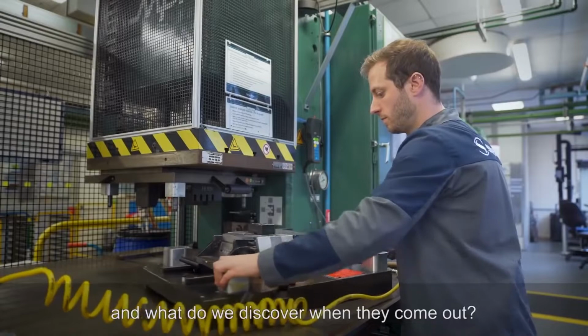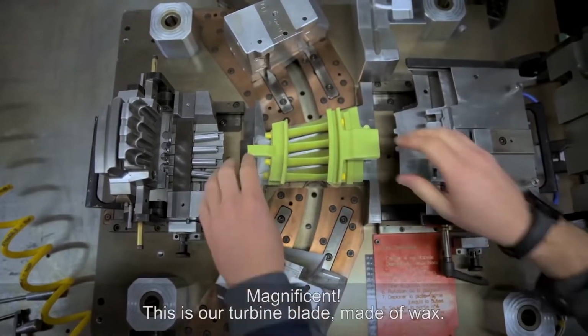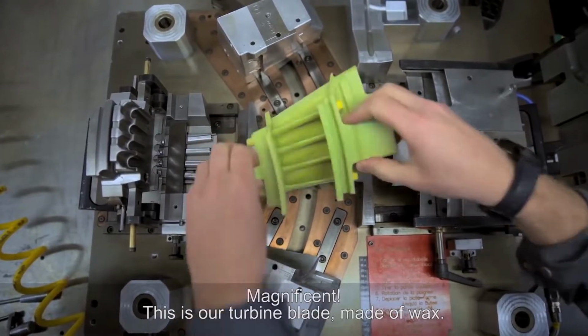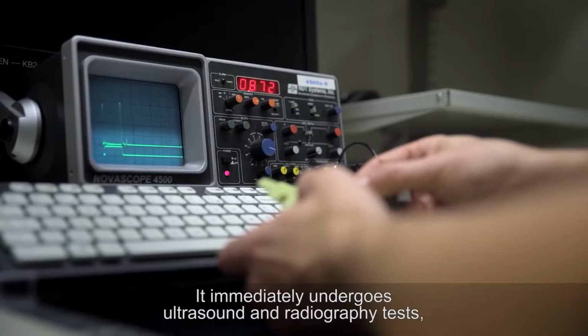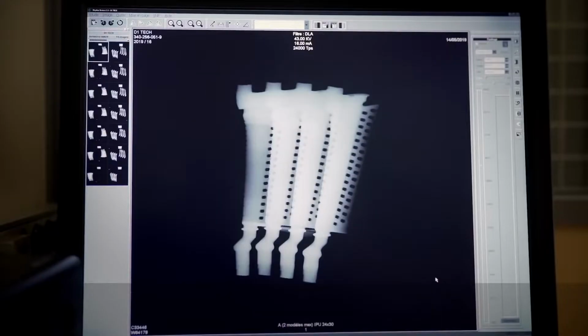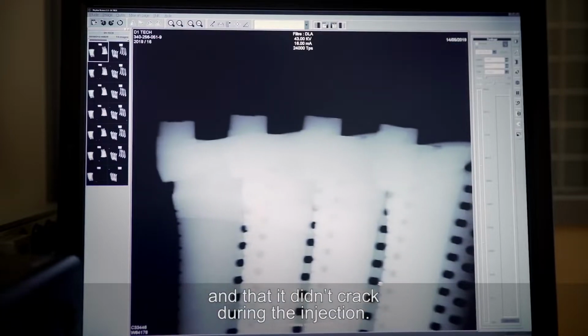And what do we discover when they come out? Wait for it. Magnificent. This is our turbine blade, made of wax. It immediately undergoes ultrasound and radiography tests to verify that the core is correctly centered in the wax and that it didn't crack during the injection.